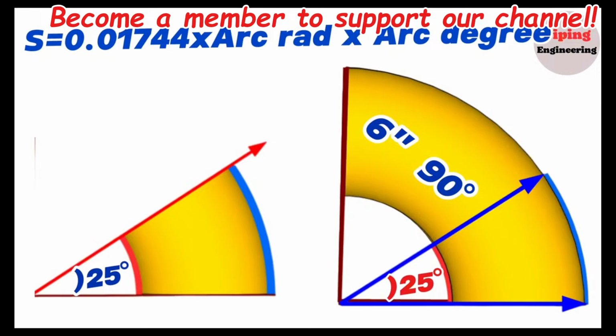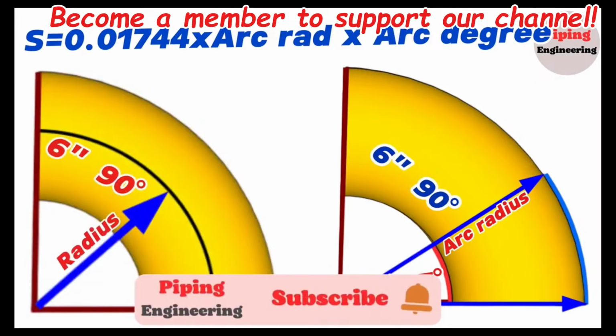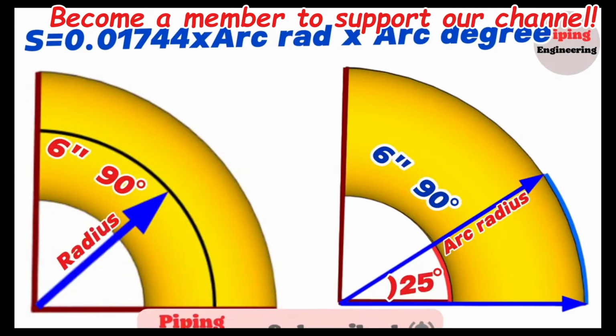To calculate this distance, we need to know the radius of the arc according to the arc length formula. If we find the radius of a 6-inch 90-degree elbow, we can easily find the radius of a 25-degree arc. The radius of the 6-inch 90-degree elbow can be found on the elbow dimension chart, or we can calculate it ourselves. Let's first calculate it ourselves and then we can check it with a chart.